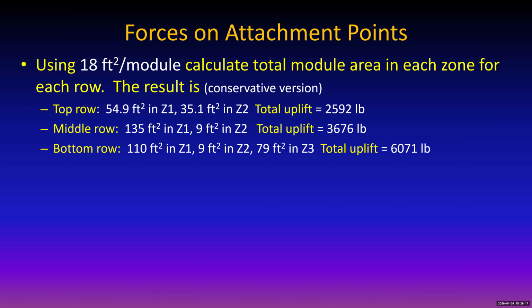Well, if you look at the reference for this, the wind load guide for southern yellow pine from the lumber industry, and white spruce and Douglas fir, it tells you if you have southern yellow pine trusses, which we have down here, then a 5/16 inch screw, an inch embedded into that truss gives you 332 pounds of holding strength.